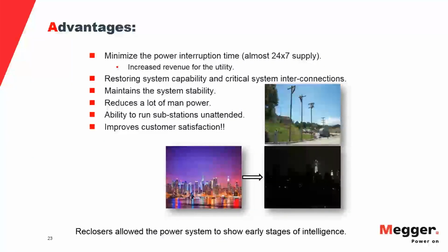If you remember the statistics that we gave at the beginning of the presentation, 80% of faults in the system are transient. I know those numbers vary from 60 to 90%, but anyway, most people agree that a good number for the transient fault is around 80%, which means that in reality, you only have to take care about 15 to 20% of the faults in the system.